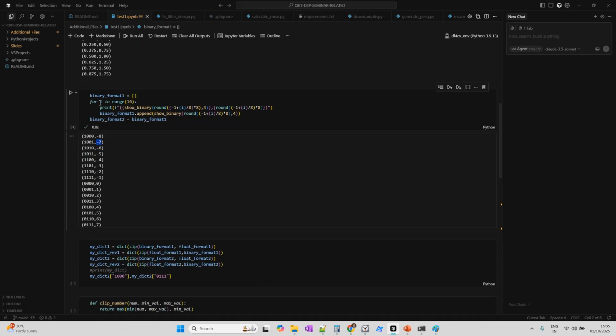These numbers, under the hood, represent different things. So finally, when we are converting into float, we have to be very careful with the Q format. If you mess up the Q format, then the outputs will be very wrong. If you are supposed to divide this number by 2 power 3 and instead divide by 2 power 4, the output will go very wrong. The RMSE that I told you about, comparing fixed point and floating point, will be very huge. We are almost making it half, so we have to be very careful with the Q formats.